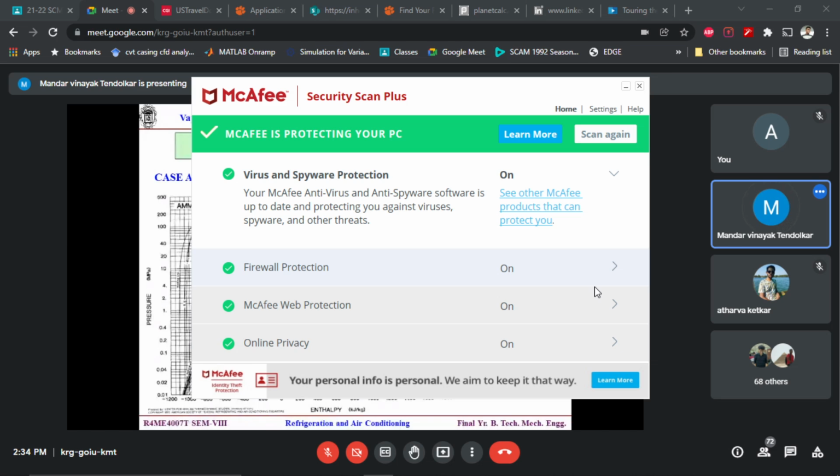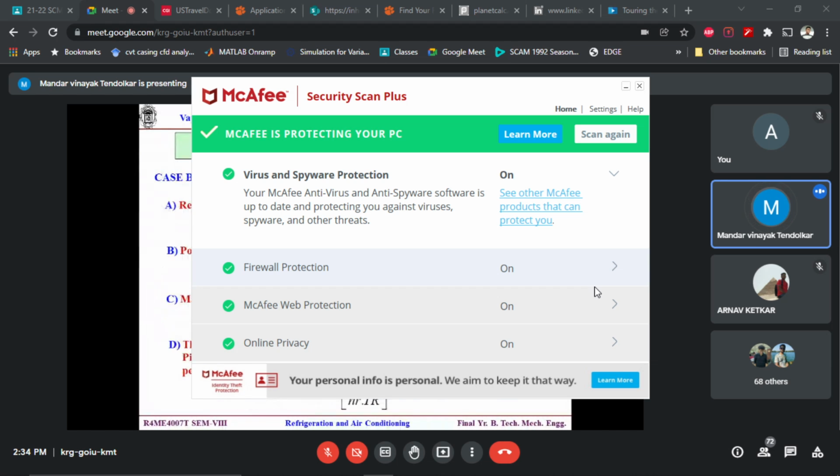Now let us see the compressor work. Fine. So now you know the H1, H2, H3 and H4. So repeat the same set of calculations. Refrigeration effect, H1 minus H4. Power consumption, that is the compressor, H2 minus H1. Mass flow rate. And here you can see that it is drastically changed. Earlier it was 0.196.